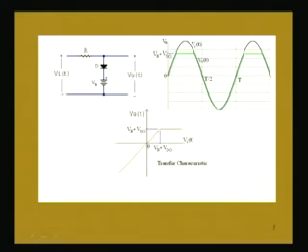that is shown here by this red line, that is this portion is for the non-conducting portion of the diode, that is from this point onwards the diode is conducting, voltage drop is constant at this voltage Vb plus Vd naught. So, this portion is the non-conducting portion where input and output voltage same, defined by this straight line passing through the origin having slope 1. So, now this is an important characteristic which we can draw from the input and output voltage waveforms.